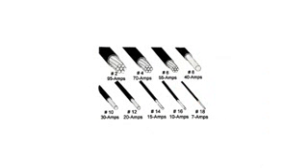It is important to choose the right gauge of wire for any given system. The greater the amperage of the design system, the thicker the wire is required. The cost also goes up with wire thickness. Some charts are available on the internet that will help you select the right wire size.